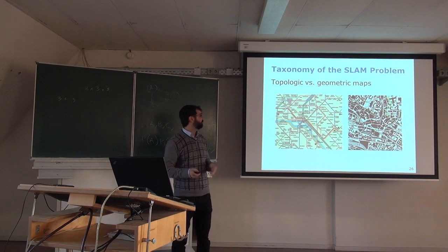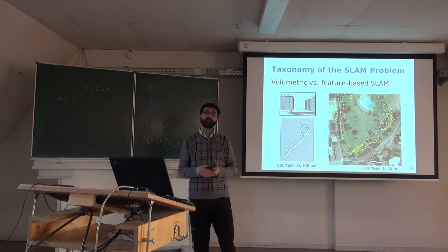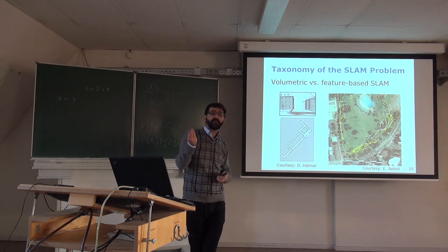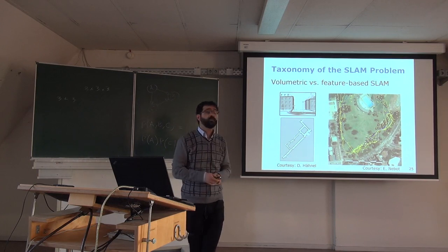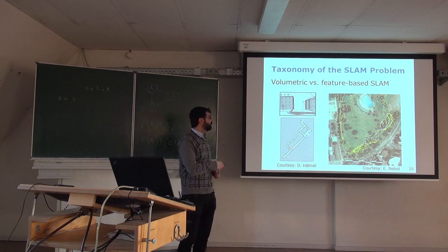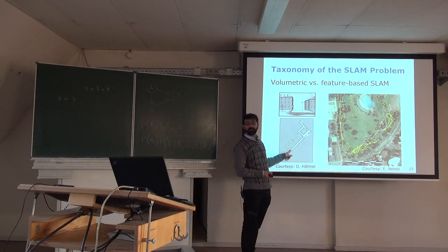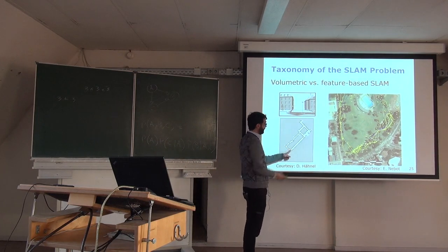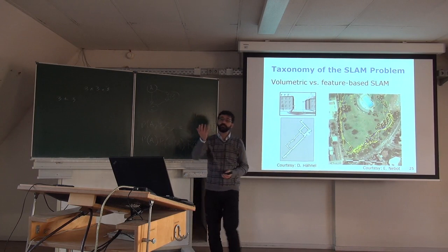as robotics, we are more often interested in volumetric representation. That's for two reasons. One is that they can give us an accurate location of the robot, but you can do it also with this kind of representation. And the second is that we can use them to do planning. Okay, so if I tell you the robot is here and I say I want to get there, he knows how to reach the place because he can actually plan a path in the free space.